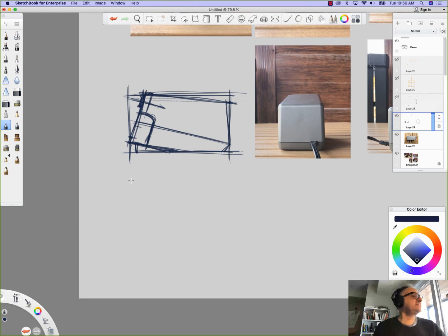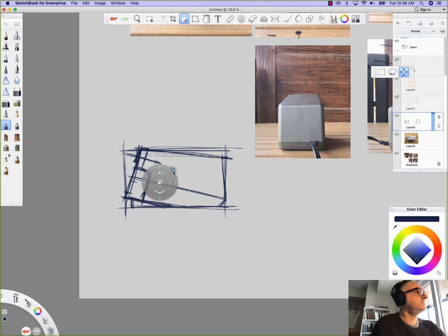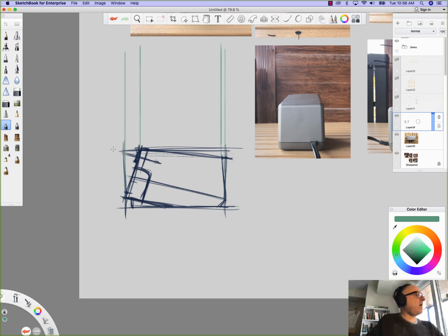What's amazing about this, now that I have this, I can draw the top view. I can draw the side view, okay? So let me just take this down a touch, bring it here, okay? So let's just do some projection lines here for a second. Watch this. From here, this edge, right across, here across, here across. And I'll do this across. Cool. I will take roughly this, okay? I don't know what that is yet because I need the front view to make the other view.